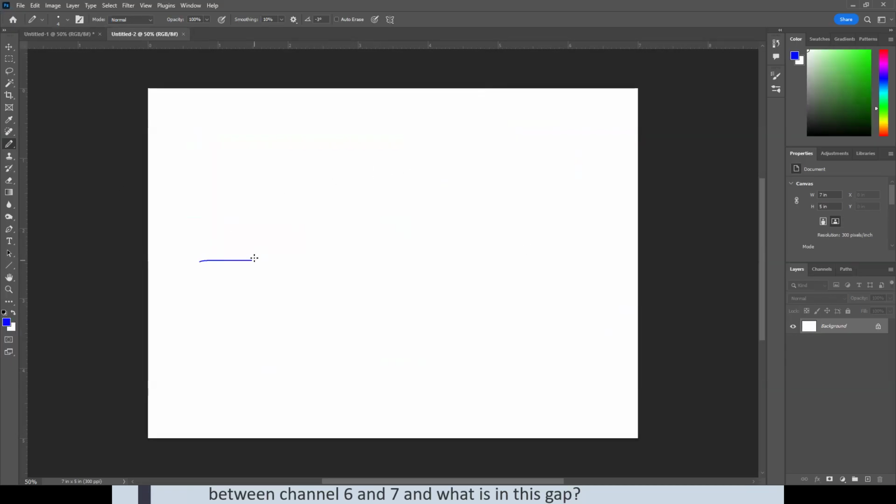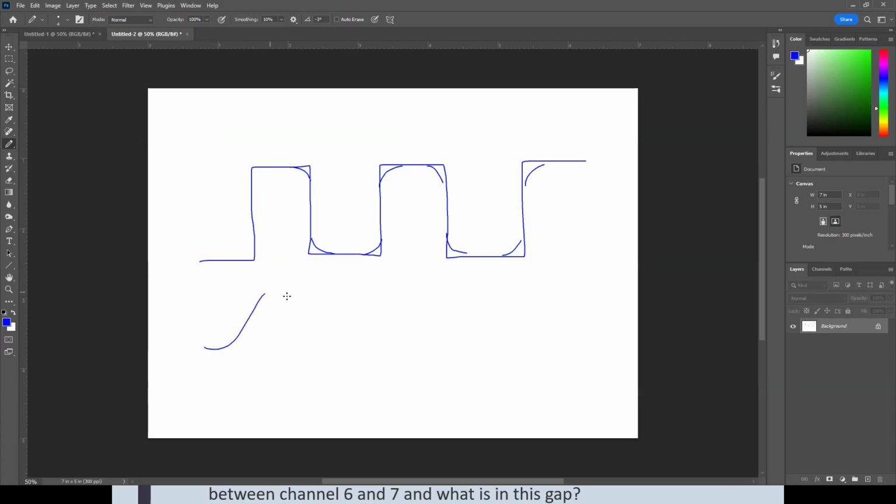Remember the square wave here? The more odd harmonics that are present, the sharper the edge is going to be. If you start cutting off some of the harmonics, then those edges are going to start tapering off because they're not going to have enough definition. It is just a matter of how much those things taper off before it starts looking like a sine wave again, right?